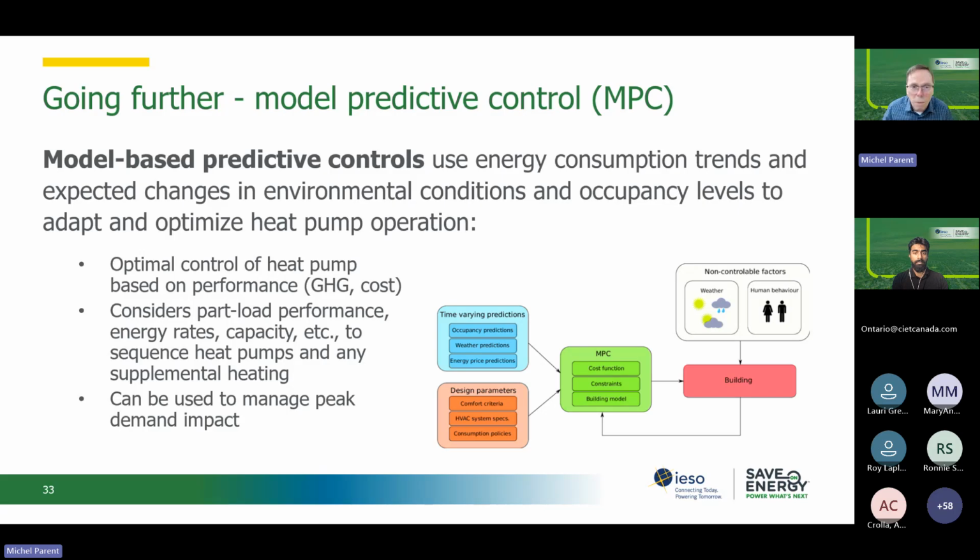It's kind of a regression model, for those of you who are used to RETScreen and regression models: a linear regression of your utility use with outdoor temperature. Those controllers use those kinds of models to predict how your heat pump should be working given the forecasted weather, and usually the day of the week.